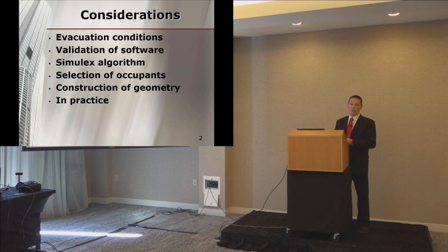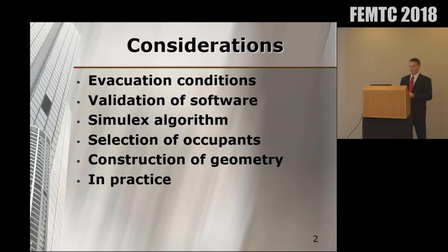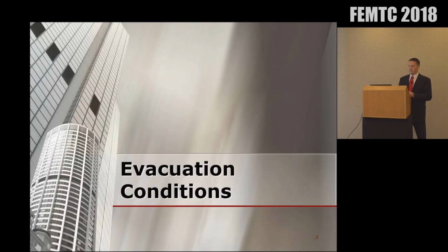You need to consider the evacuation conditions. Certainly the software itself, is it validated? We'll talk about the Simulex algorithm and how it would play into the scenarios, how you select the occupants, the geometry, and then we'll hit some case studies.